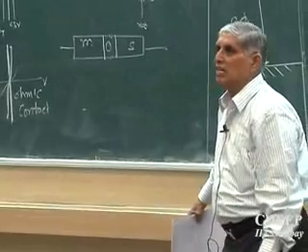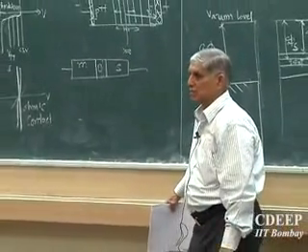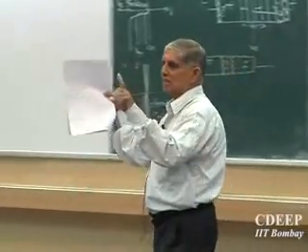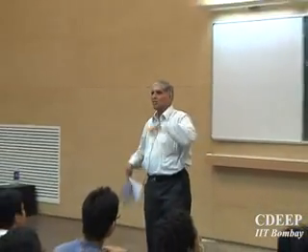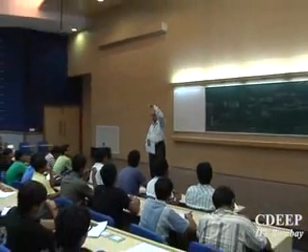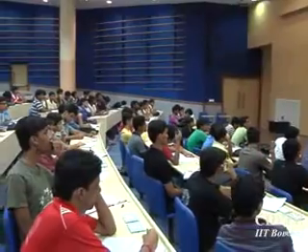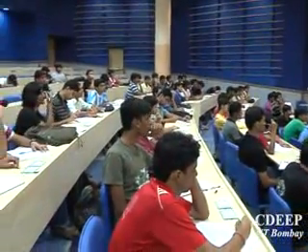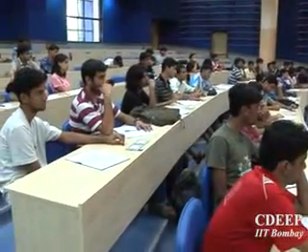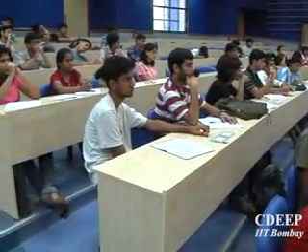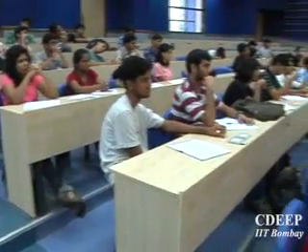Now this insulator creates a problem different from the Schottky barrier. In a Schottky barrier, as soon as I touch the metal, electrons went and the Fermi level aligned. Now there is another material in between whose Fermi level I also don't know because it's an insulator. Why do I say I don't know the Fermi level in an insulator? Because the band gap is so large, 8 electron volt, 9 electron volt, and where is its position from the vacuum level? So depending on that, if all 3 Fermi levels have to align, whether the carriers can go from metal to semiconductor at all will be seen.